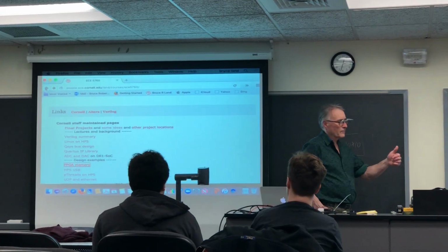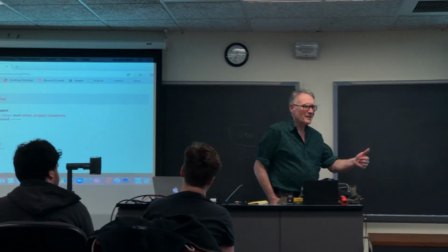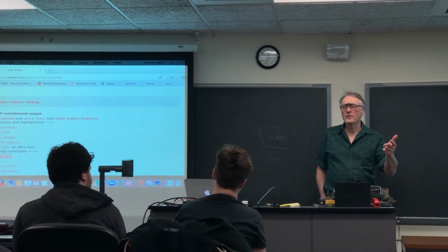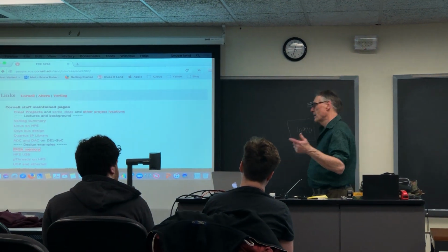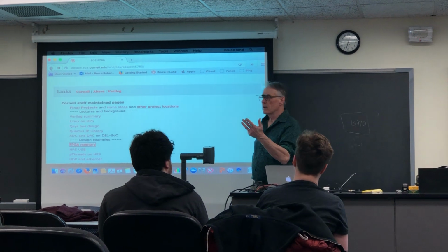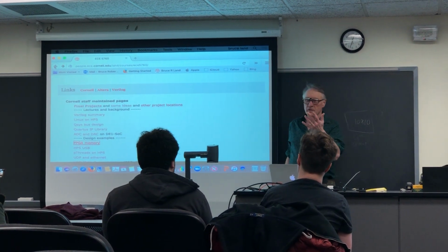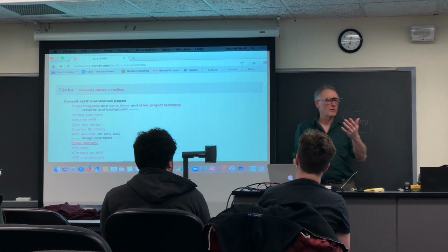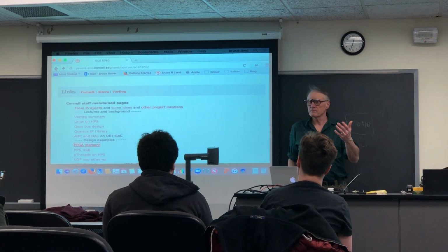Trade-offs here are memory capacity, memory bandwidth, number of logic elements, and number of multipliers. And of course, there's a time constraint. You have to get done with a sample within 20.8 microseconds.